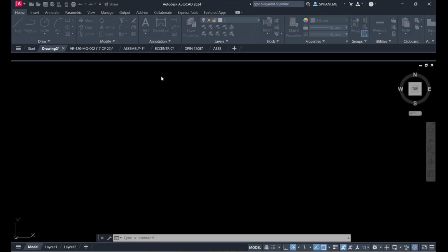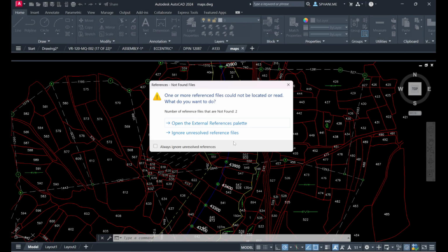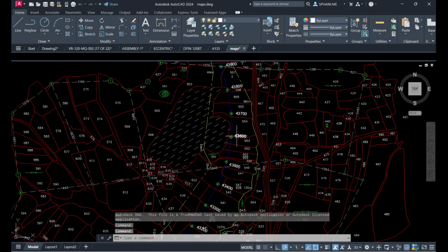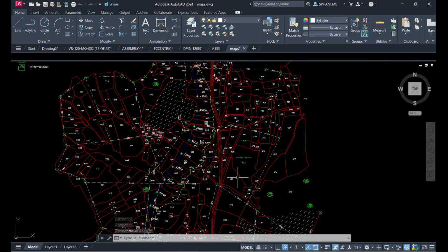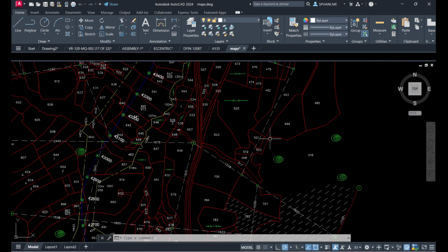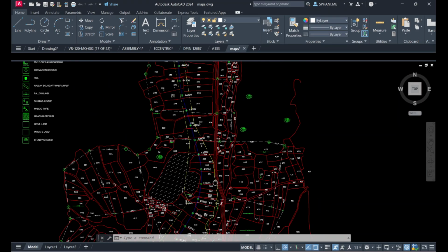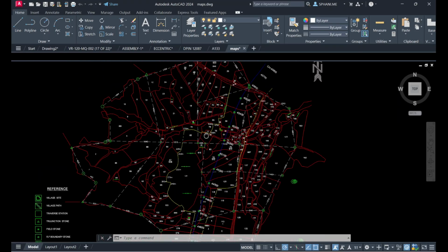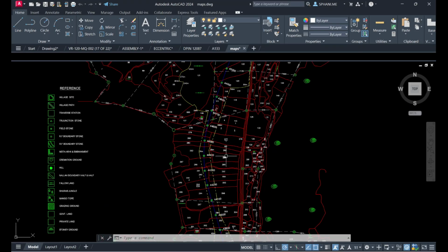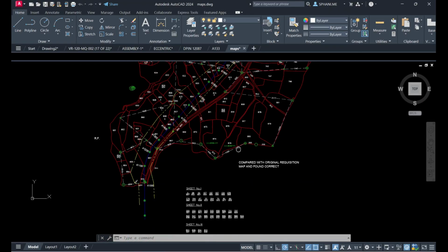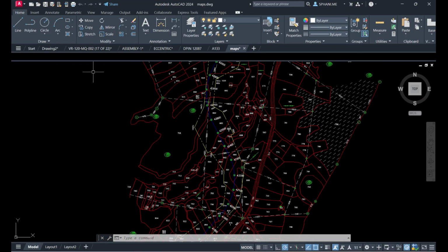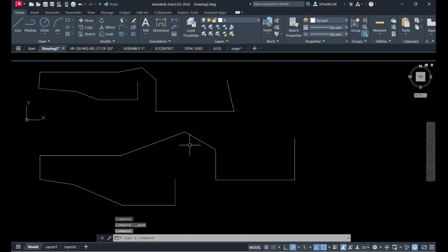Maps. See, if you observe this, these are the polylines. Or sometimes we may use spline, I will explain that later. Either polyline or spline, you can draw these map diagrams. By using AutoCAD we have to draw this kind of map drawings. Okay, go to our drawing.